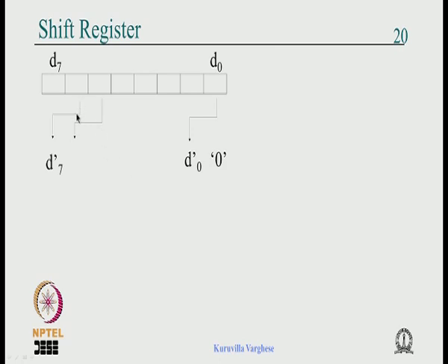You take D6 as the shifted version for bit 7, D5 is used as bit 6, and so on, down to D-1, and you append a 0. So basically when you say shift alone, it is just wiring.